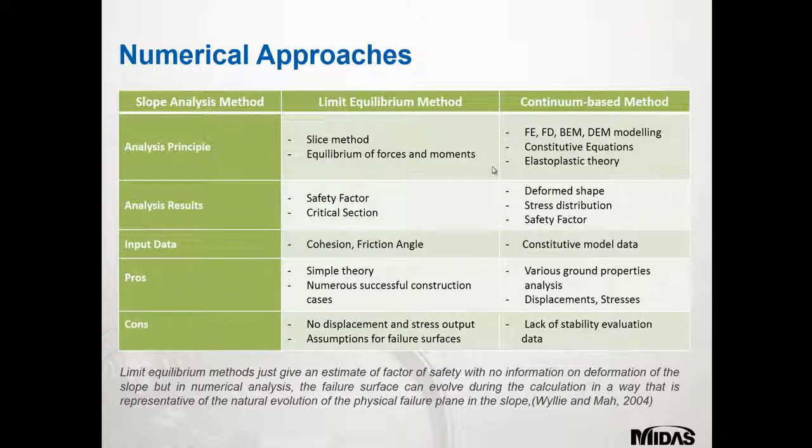Constitutive equations for ground and structure and elastic plastic behaviour are all included. So the LEM only gives results for the factor of safety and force diagrams for each slice, but continuum based methods give additional results for deformed shape, stresses and strains in the ground.